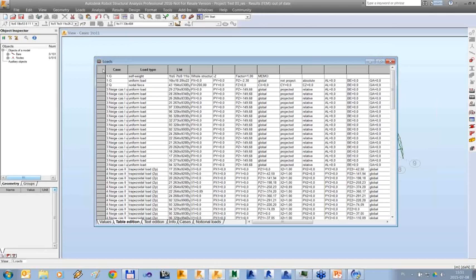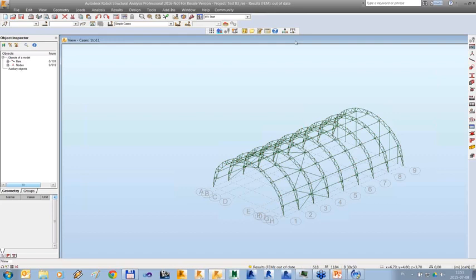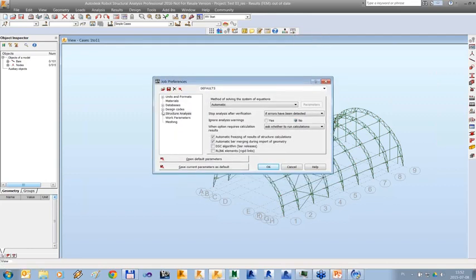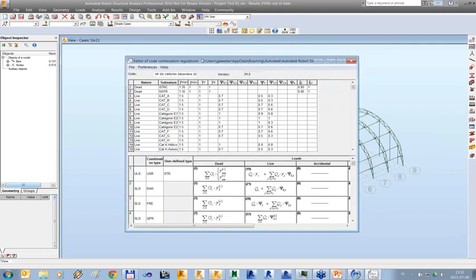There is one question about showing one more time where you can edit loads combination. I guess, how to create code combination regulation. So, once again, first of all, our recommended way is to modify an existing regulation file from our list. So, job preferences, we can activate loads here, select any code combination regulations file, and then use the three dots button to run our internal editor.